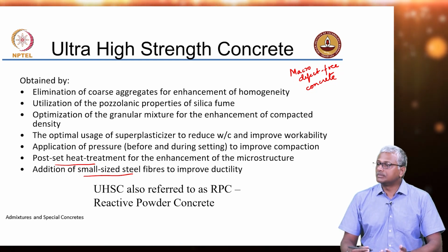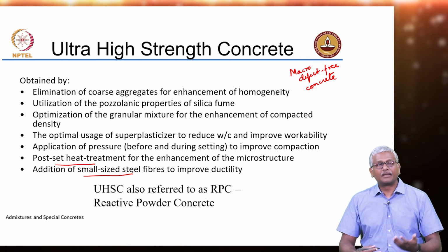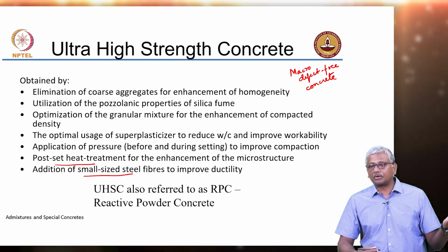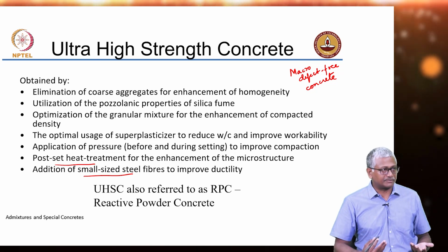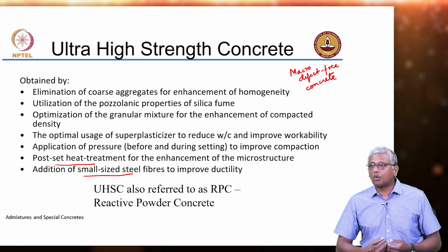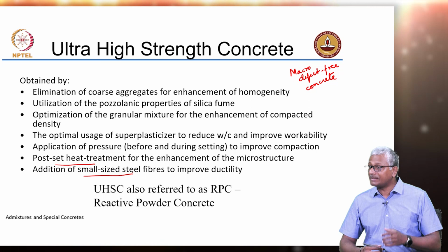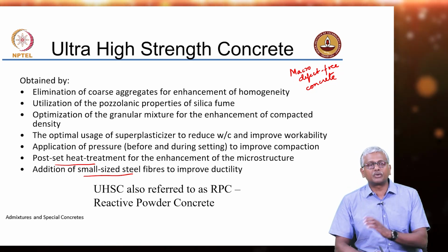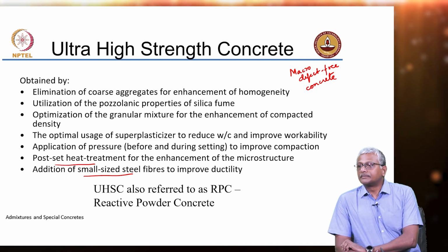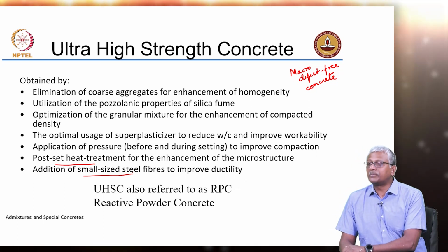Now, as we saw earlier, when you increase the strength of concrete, it becomes more and more brittle. It loses whatever little ductility it can have. Okay. So you want to enhance the ductility, but yet achieve a very high strength that can be only done with the help of fibers. Why? Because what do fibers do? They bridge the cracks.